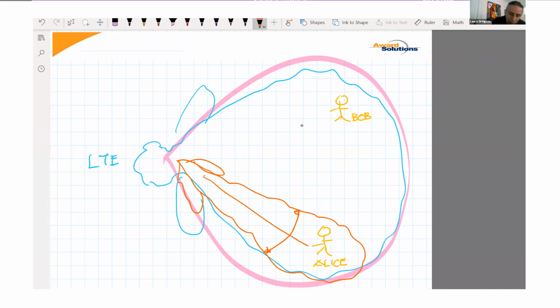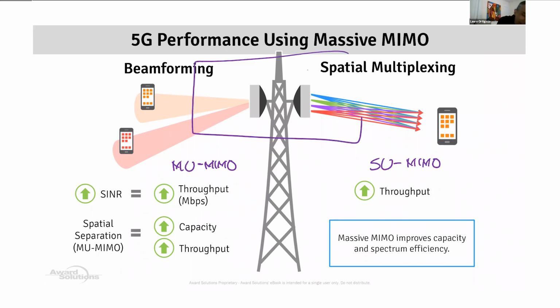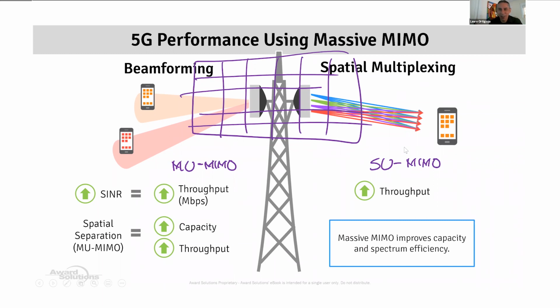Okay, so really quick, guys. What happens when we compare the propagation characteristics in frequency range 1 versus frequency range 2? Okay, so there's going to be some differences, right? For those of you who have been working with LTE, UMTS, 1xEVDO, and all that jazz, we know that in frequency range 1, we have line of sight, reflections, diffraction, and scattering. All of these are actually very good in order to get coverage.